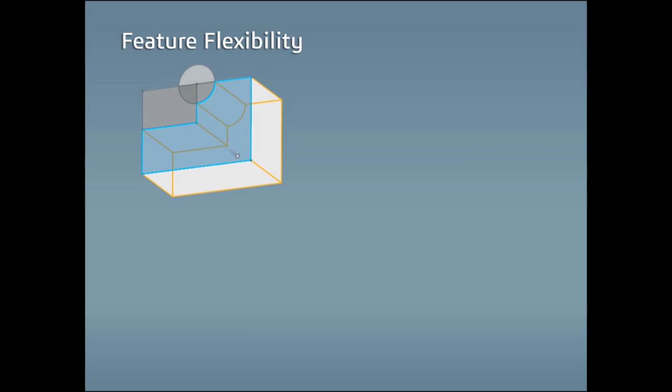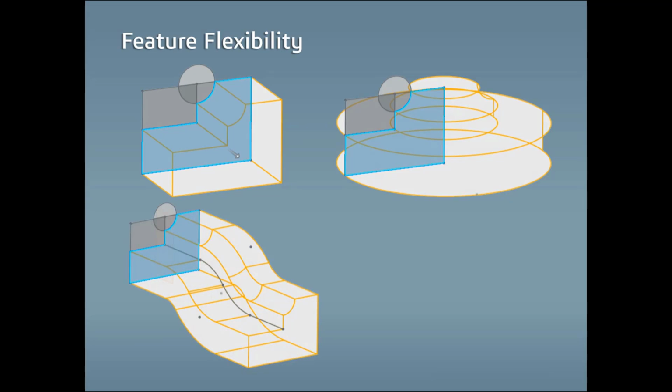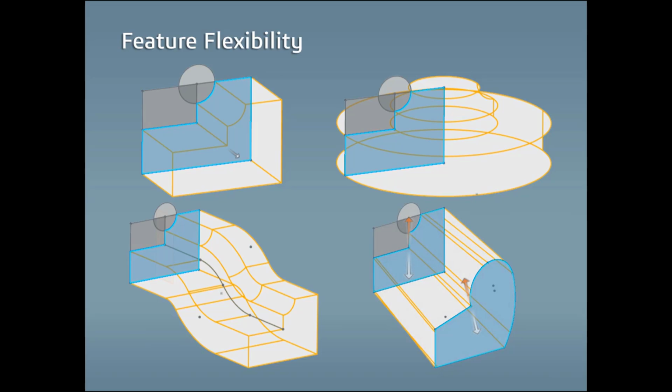For instance, an extrude feature takes the sketch profile and moves along a line that's normal to the sketch profile. A revolve feature takes the sketch and moves it in a circle. A sweep feature takes the sketch and moves it along a custom curved path, which typically uses another sketch to define the path. And the loft feature connects two or more sketches together, creating organic, curvy geometry. To successfully make these different feature types, it's important to know how to edit sketches properly and change feature options as needed. I'll switch over to xDesign to show you some of these techniques.